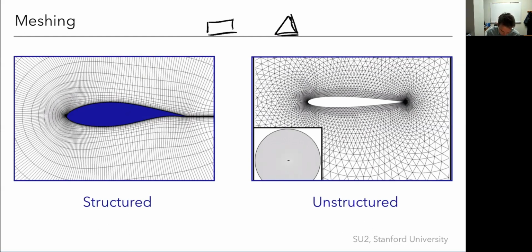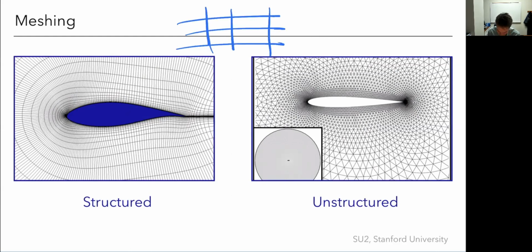And so there are two ways to do that. I'm going to do the rectangle way because this can be maybe easier to visualize. So I've got this mesh here. I've got some governing equations, and let me just write the 2D mass equation. So let's just say d(rho u)/dx plus d(rho v)/dy equals 0.